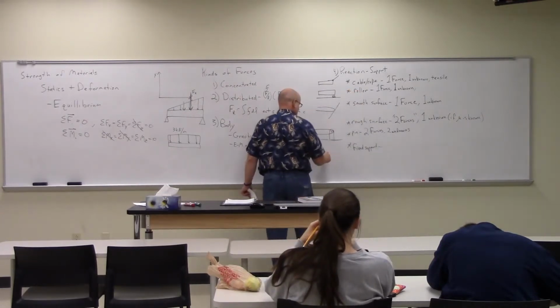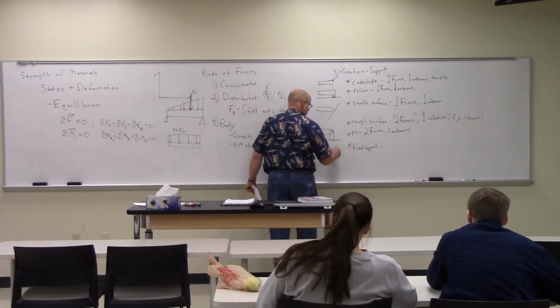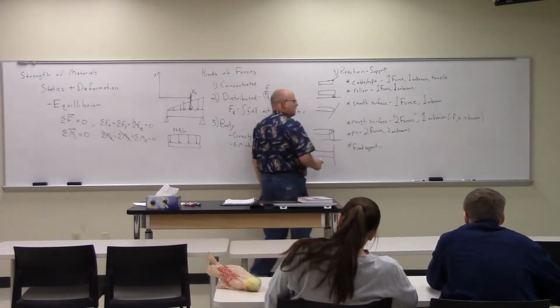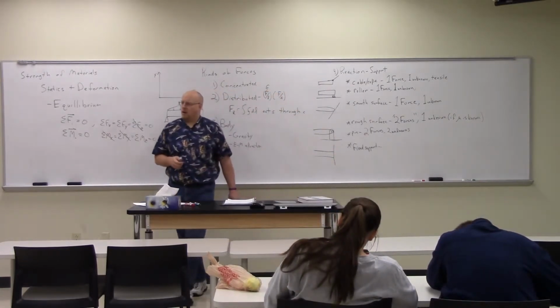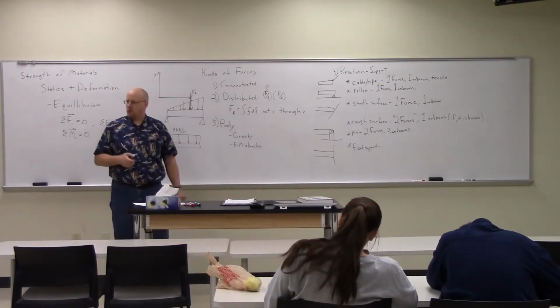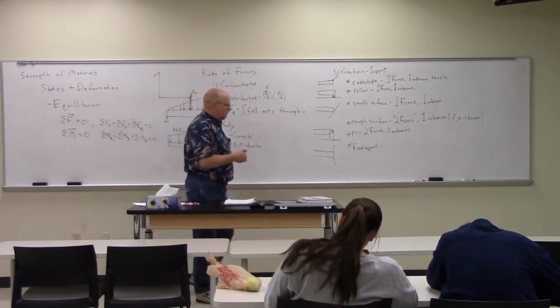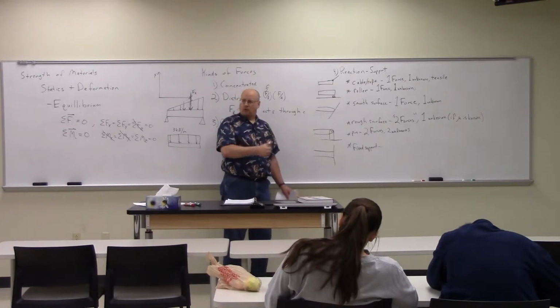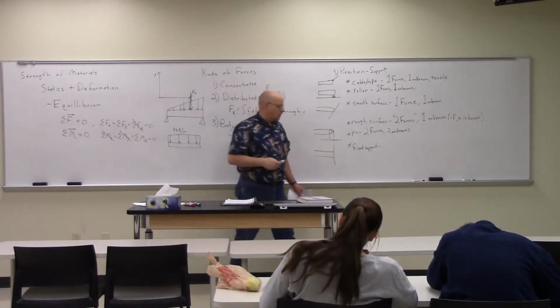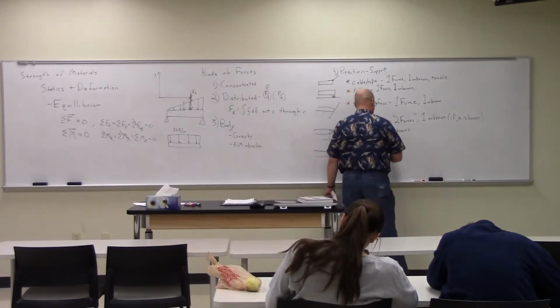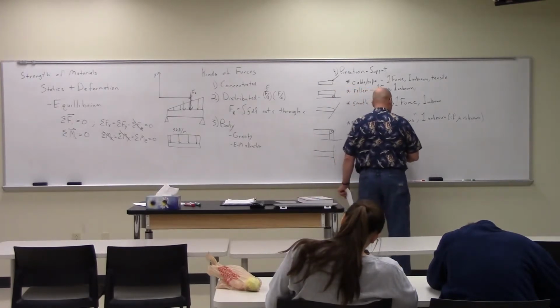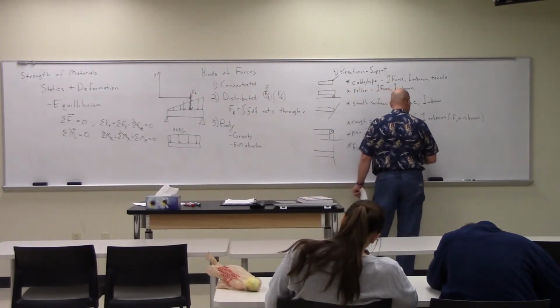I sink it in concrete, and just embed the bar in the supporting surface. Now, not only can it support vertical and horizontal forces, but it can also support a moment as well. So now we have two forces, one moment, and three unknowns.